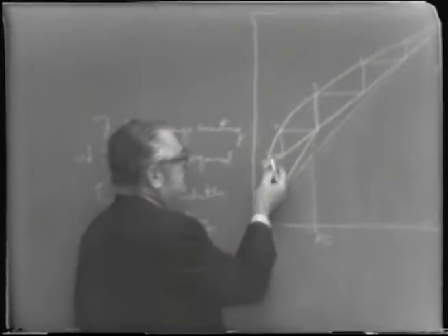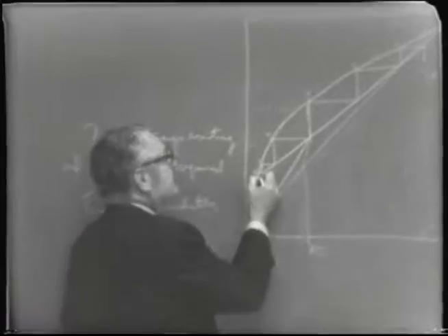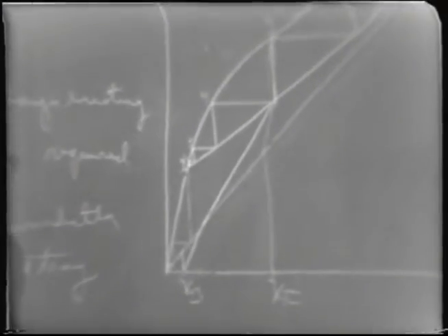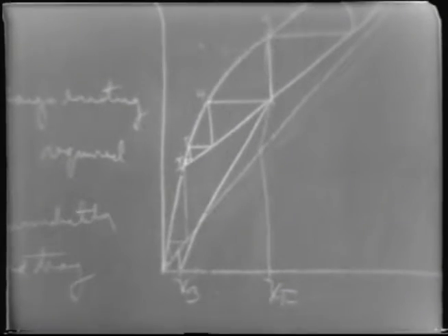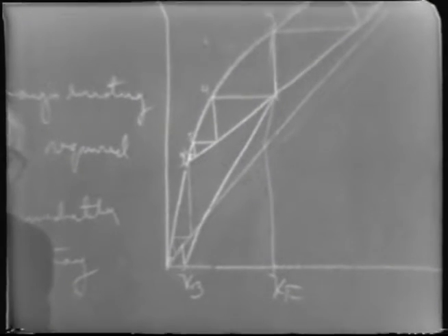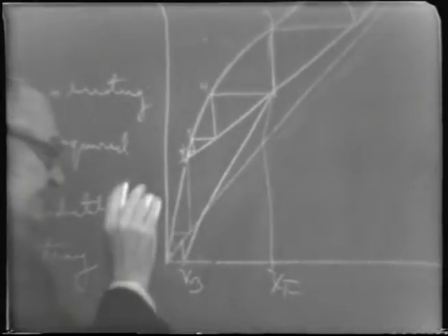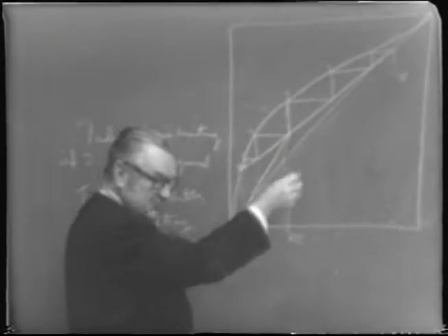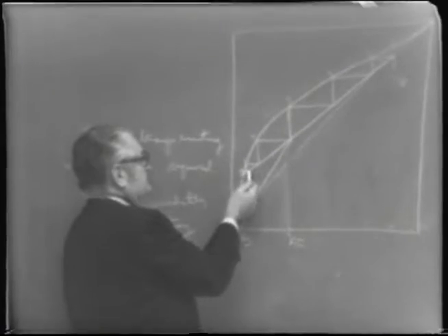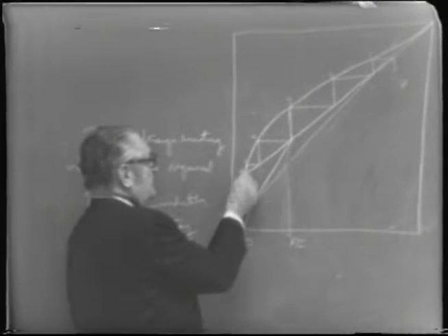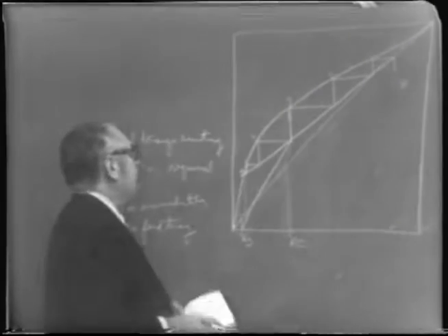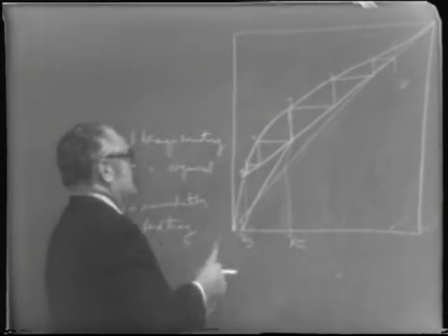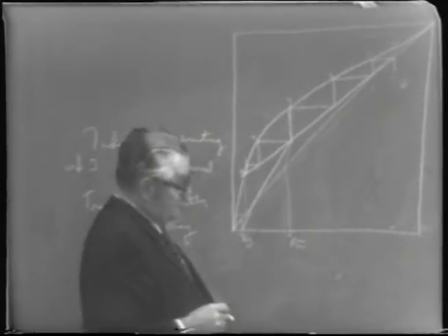And you can notice also that in a situation like that, the steps have become very small. Very little change in concentration is taking place. We call this a pinch situation, or a series of pinch trays, because the conditions of the graphical solution to the McCabe-Thiele equations require it to be represented as I have here.